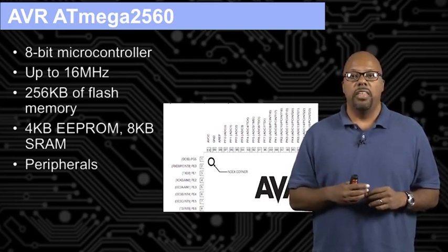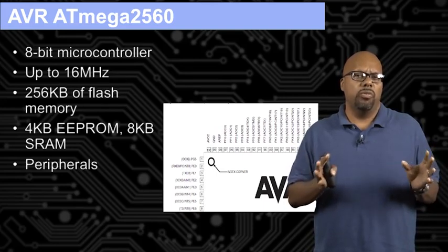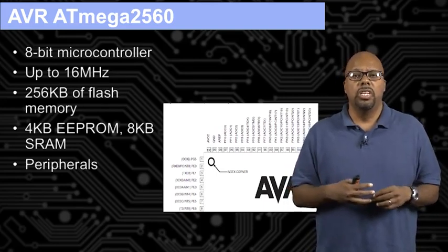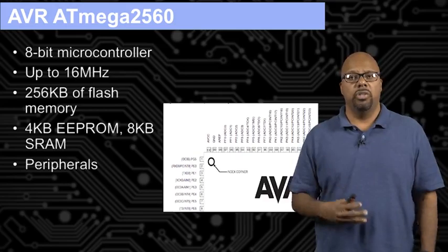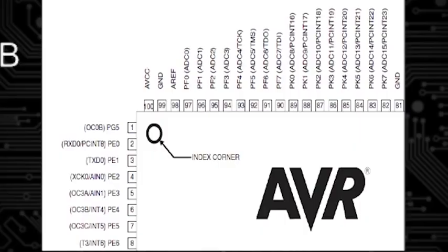We'll talk about that. And then peripherals is sort of a general term for all the other components inside the microcontroller on the chip, like the timers, A to D converters, and all those other things. So it's got a number of peripherals that I didn't list. I didn't put the whole data sheet up there. But that picture right there shows you what the pins look like, so actually where they are configured on the chip. So if you bought the chip, which pin corresponds to which function, and they're all labeled right there. Actually, this is just a snippet of it because we couldn't put all the pins on this one page. That's like the upper left-hand corner of the chip. It shows you the pins that you can see there. And there are a lot more pins than that, but they're all labeled with names that are referred to later in the data sheet.